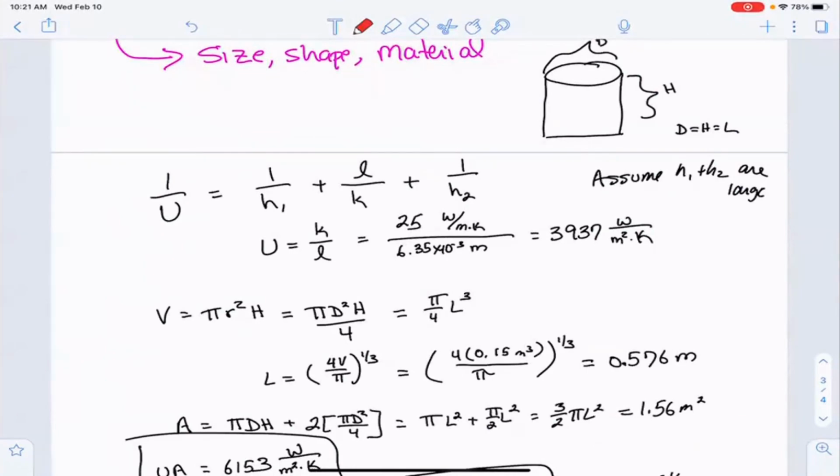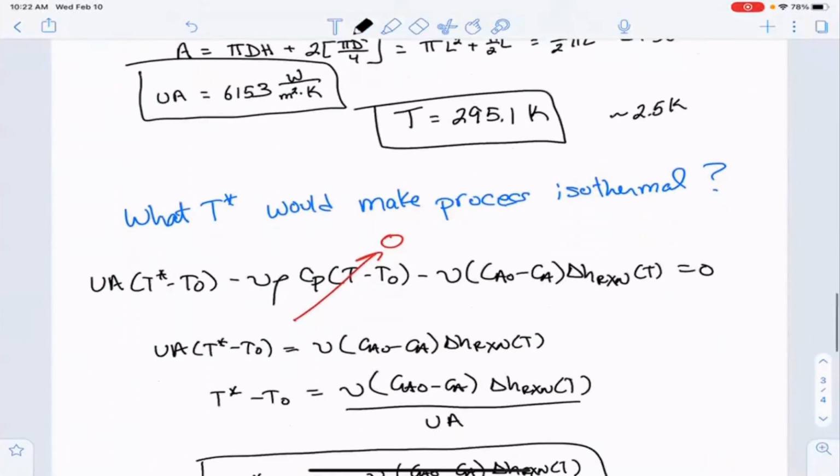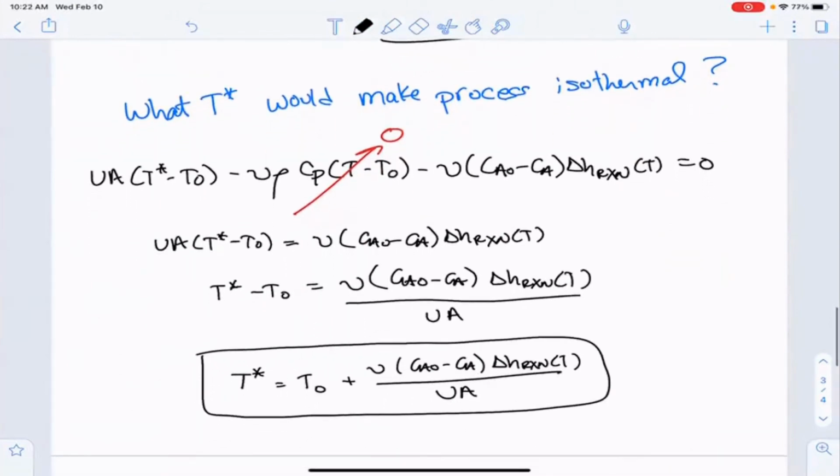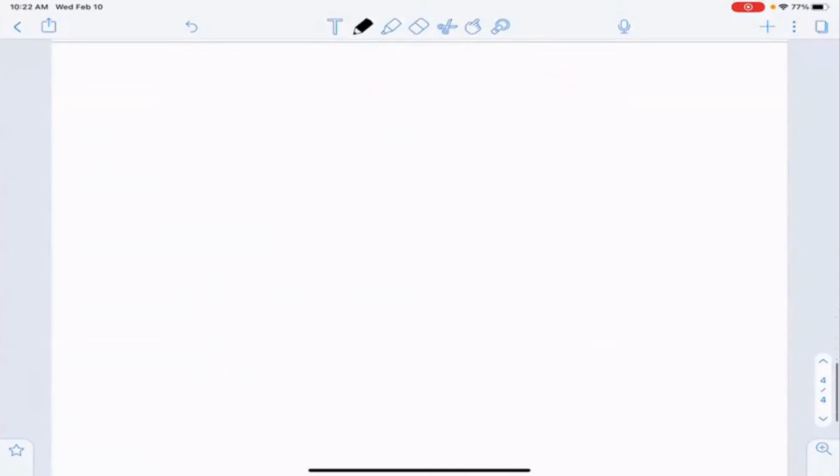And spherical reactors, if you were to Google this, you can find spherical bottom CSTRs. And they're trying to do this. They're trying to maximize heat transfer. They're also trying to do things with mixing as well. And spherical shapes are great for things like this because they have the largest surface area to volume ratio. But sometimes the implementation is difficult because you have unused space and other things. But I think that was an interesting way to think about it in terms of the resistance. So that was very nice. Okay. All right. Any questions before we do sort of the last module for today?